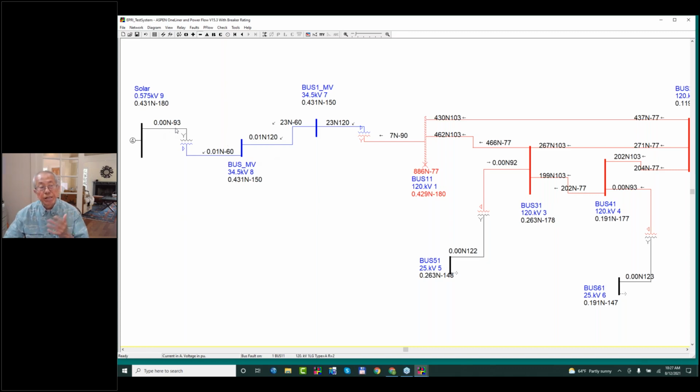And if they did that, then there will be a negative sequence injection, and that injection is always 90 degrees ahead of the zero sequence voltage phasor. Now, why is that important? Why is that negative sequence important? Well, because a lot of the relaying in North America is based on negative sequence. So if you have things that inject zero negative sequence current, that could present a problem. So I know NERC has been very concerned about this and has held several meetings already with utilities and with relay manufacturers to discuss this. And so I expect that within the next few years, you will see negative sequence coming out of these machines.